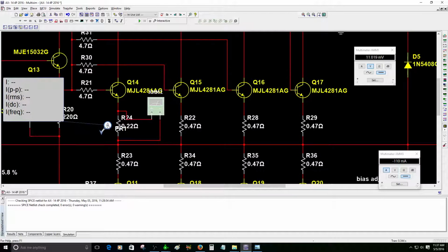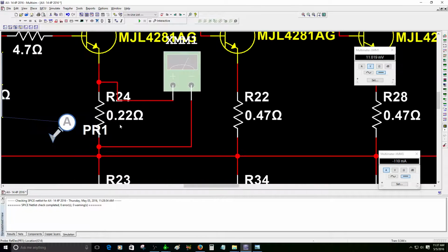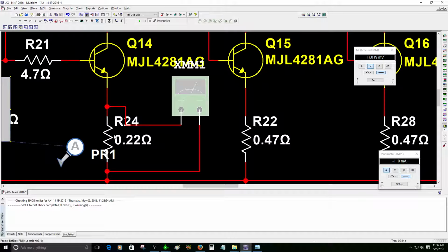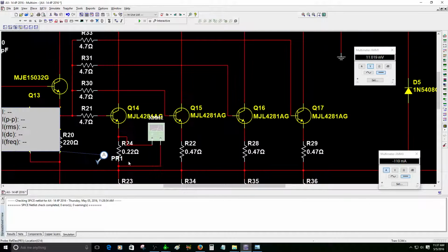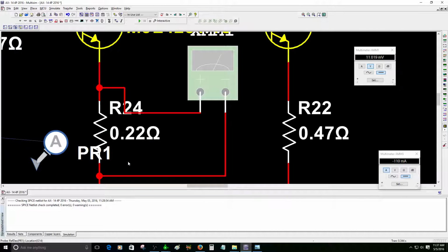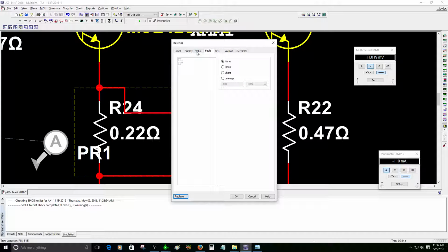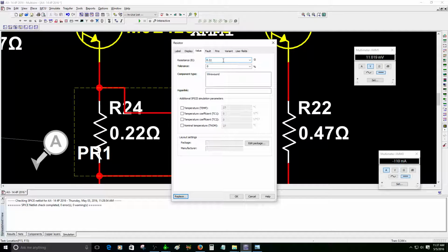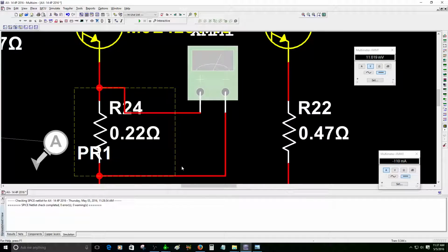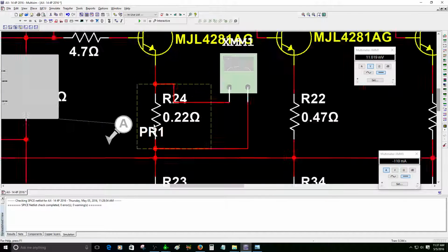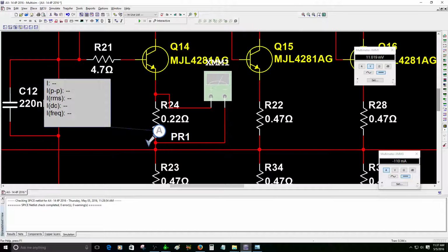It was really interesting because this resistor, the emitter resistor, it's this one right here, it's kind of difficult to find the 0.22 ohms. So I decided to change that to 0.47. While I was doing that, I noticed that the adjustment of the bias was totally different. One example, I'm going to do it right now here. This one here is 0.22 and the result is different.